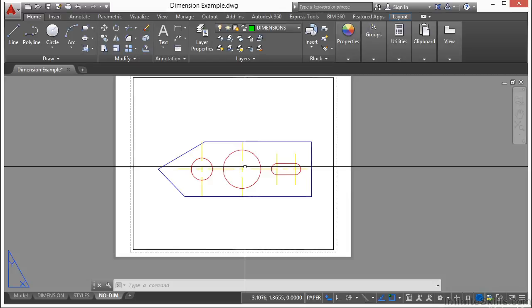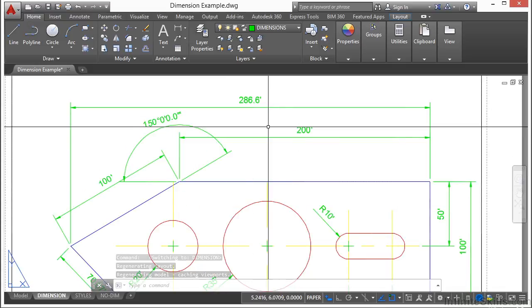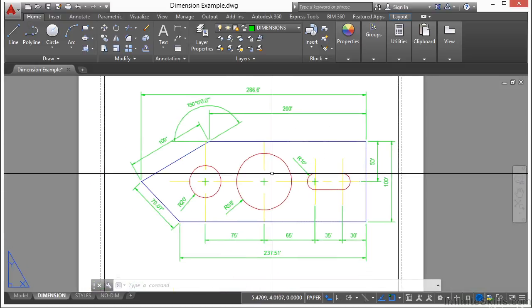You can create dimensions for a variety of object types in many orientations. Linear dimensions can be horizontal, vertical, aligned, rotated, a baseline, or a continued or chained string of dimensions. Here we have several dimensions on this bracket. Dimensions can also be associative, non-associative, or exploded.